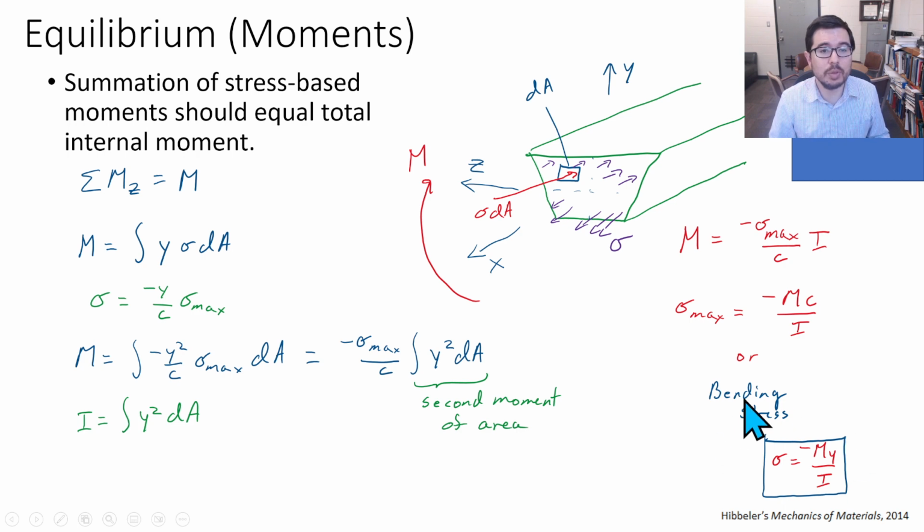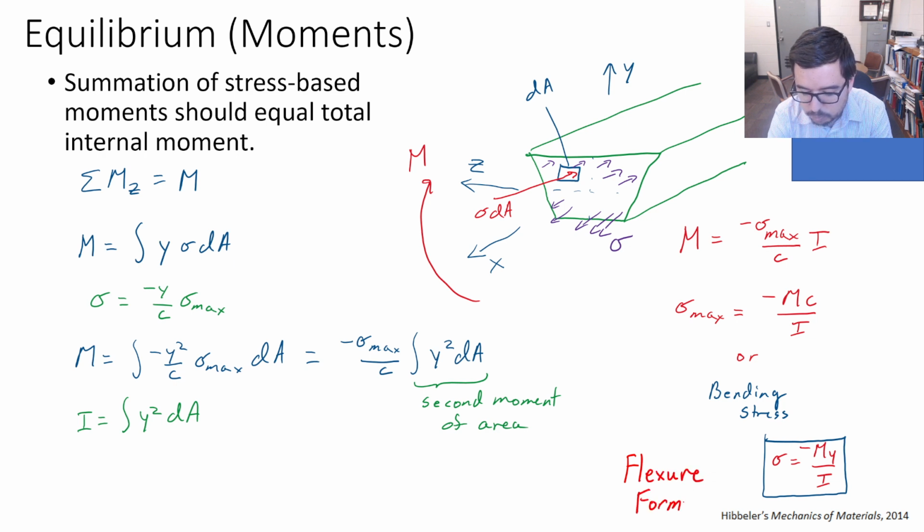This is a huge equation. This is one that you want to remember if you're going into a job interview, okay? Because if you have a beam and there's some bending moment that you can calculate, you're able to calculate an axial stress. And it actually has a special name, called the flexure formula. So this is definitely one to write in your notes or memorize.